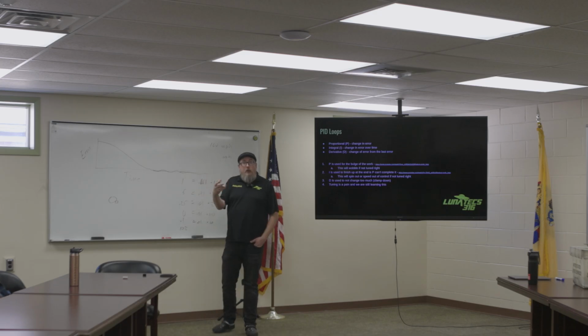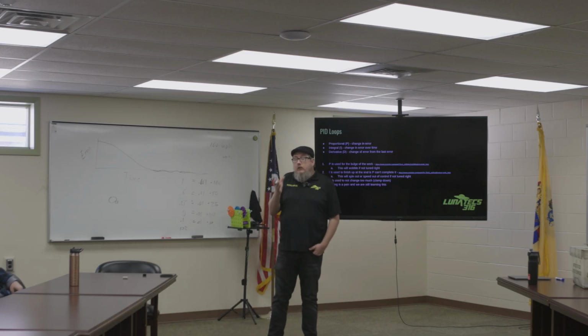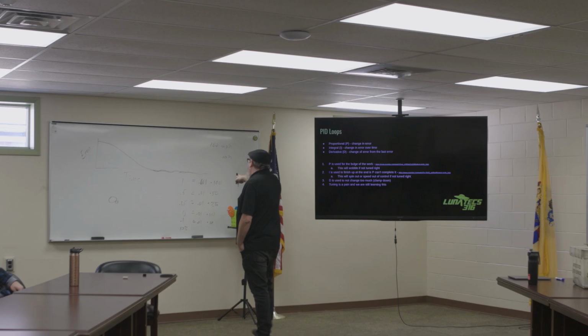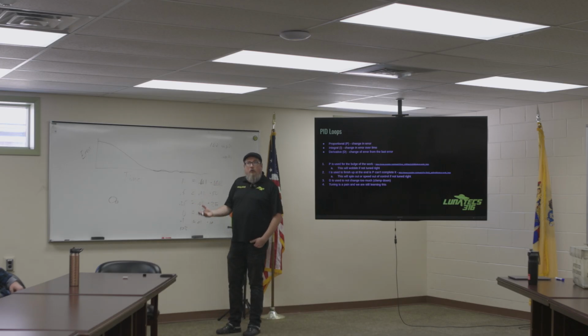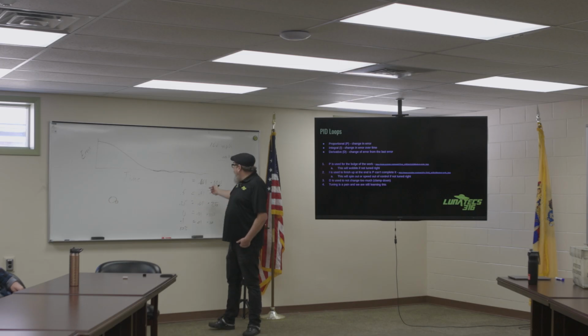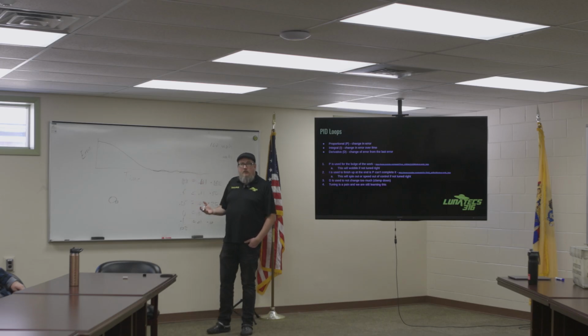I don't want it to go at 100%, because maybe that hurts the engine. So let's say I multiply by 0.001, so it doesn't accelerate as fast. It's a slower acceleration, right? Because if I'm at 100 error, now I'm giving it 10% power. Does that make sense? Because when I'm at 0, I'll give it 10% power.